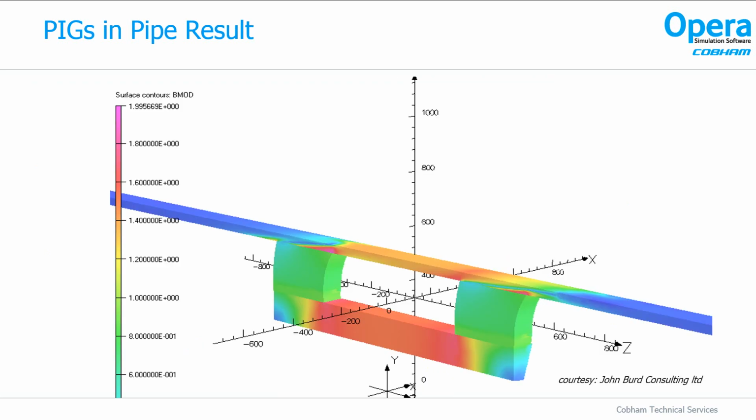When a magnetic PIG passes through the pipeline, the section of pipe will experience a change in magnetic flux, and since pipe steel is a good electrical conductor, an EMF will be generated in the wall. This will give rise to eddy currents circulating in the pipe wall, and these, in turn, will generate magnetic fields opposing those generated by the PIG. The greater the velocity of the PIG, the greater the eddy current effect will be.